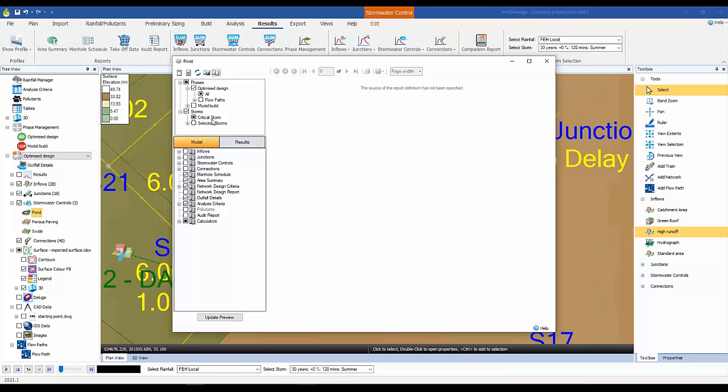And I think this is a tremendous improvement in that it's no longer necessary, or no longer aimed towards producing hundreds and hundreds of graphs. We really only want to see the graphs associated with the critical storms. I'd mention instabilities again: if you want to see those graphs, make sure you're looking for a smooth graph. If you see a lot of oscillations, then that's a potential instability that should be investigated by our support team based in Wallingford.